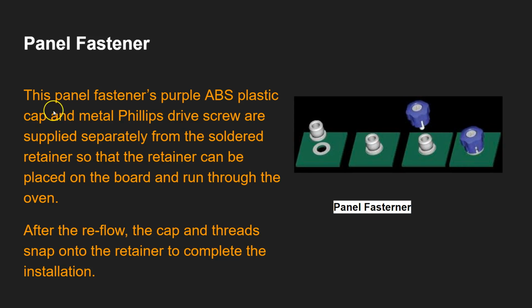So here you see the panel fastener, with plastic caps and metal Phillips drive screws supplied separately from the soldered retainer, so that the retainer can be placed on the board and run through the oven. After the reflow, the cap and the thread snap onto the retainer to complete the installation. So that's how it is installed on the PCB.